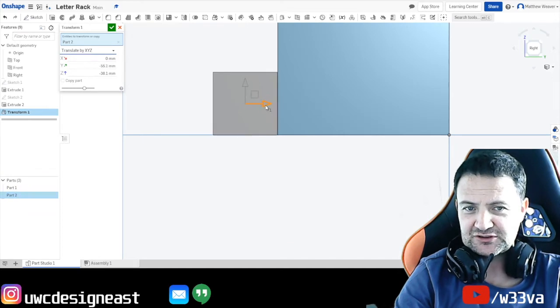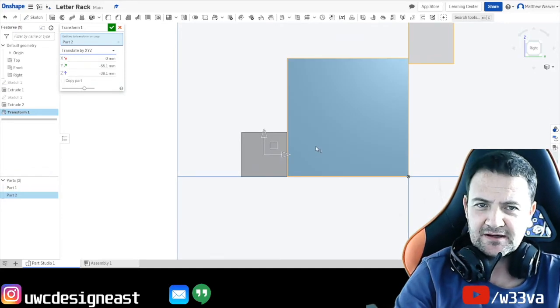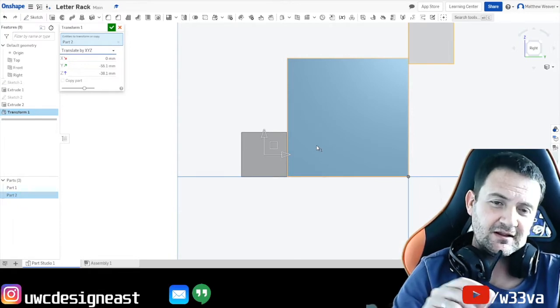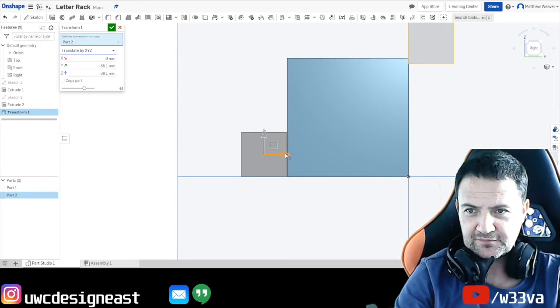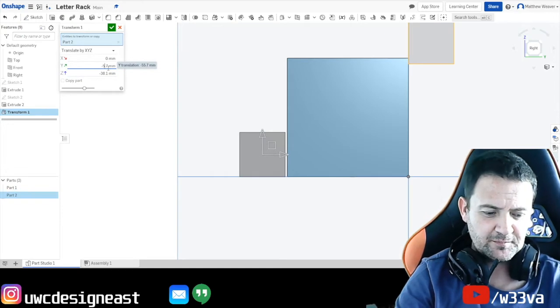Now I know I'm going to have some shapes in the middle of these two pieces, and I know that those shapes are made from the MDF, and I already have been told, and I will get told, and I'll research it, that the thickness of those shapes is going to be 3 millimeters. Okay, so if I click this one, can you see Y is changing? So if I just move that to about there and actually add 3 to it, so that's 55.1. If I just go 55, can I do that? And that would therefore be 58.